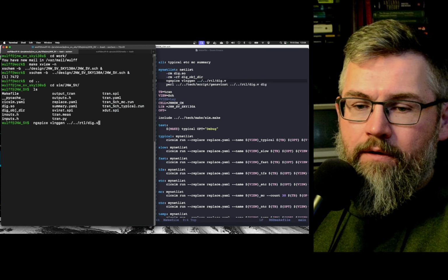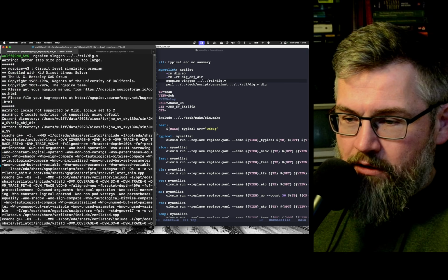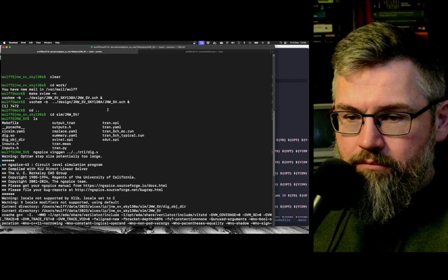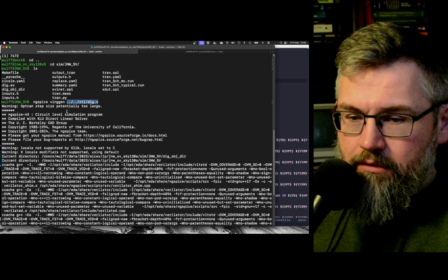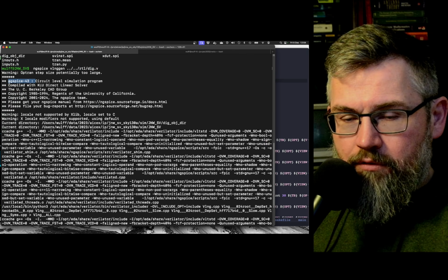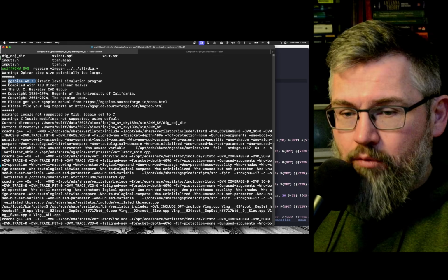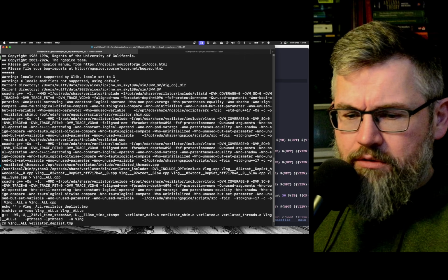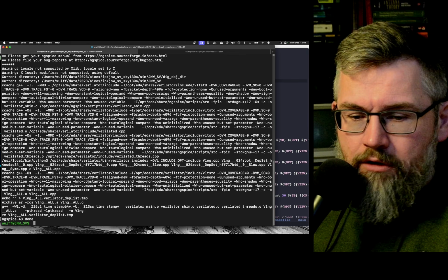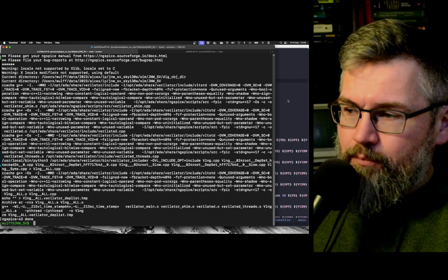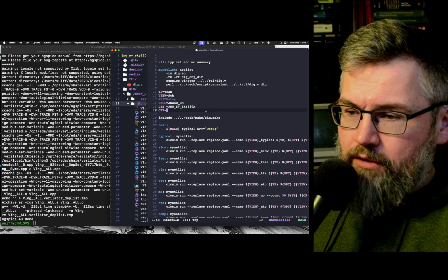Here Ngspice is using Verilator in order to compile the Verilog. It'll take the digital design we looked at as the input. It's important that you use Ngspice 43 and up. In the older Ngspice versions, it will not work. Or maybe it was introduced in 42. I don't know, just use the latest one. If you don't have it, then you have to compile it. What this will do is make an object directory. Actually, let's open that.